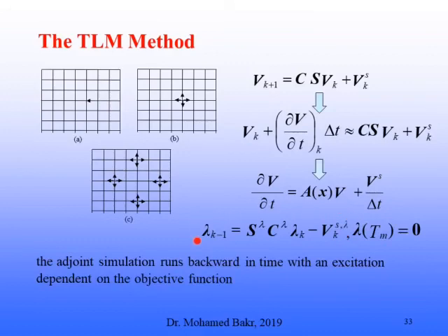You see that this is the adjoint system that we get at the end. This one here is running forward in time. This one is running backward in time with terminal values, as we agreed earlier. But using these two, you can get the sensitivity of really any objective function. And we did apply this method to many objective functions, including S parameters and energy and so on.